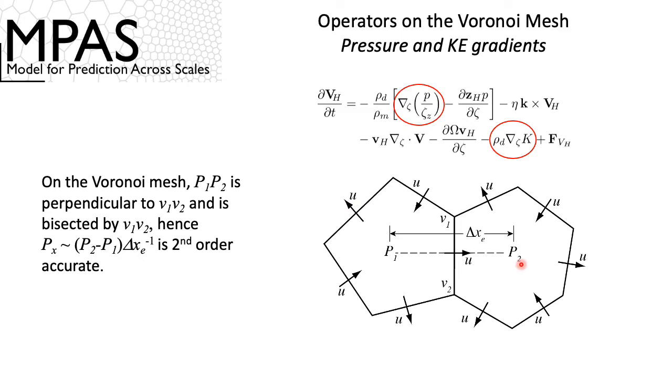This is the same operator that regular grids, which have rectangular meshes, use, because they've got a global coordinate and the velocity is tangent to one direction in that global coordinate, and typically the pressures and densities, etc., are located at the cell centers, and they have the same property. But now, in this much more general mesh, we also have the same property for the C-grid discretization in the horizontal momentum equation. That C-grid discretization means we're solving for this normal velocity at this cell face. So that's what we're doing in this C-grid approach.